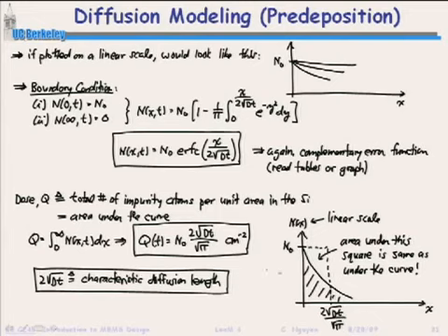the length or the depth at which you have a box that has exactly the same concentration as what you would get if you integrated, exactly the same dose, number of dopants, as what you would get if you integrated infinitely into that silicon. Okay? So it's just kind of a characteristic length. You see these all over the place in semiconductor physics.